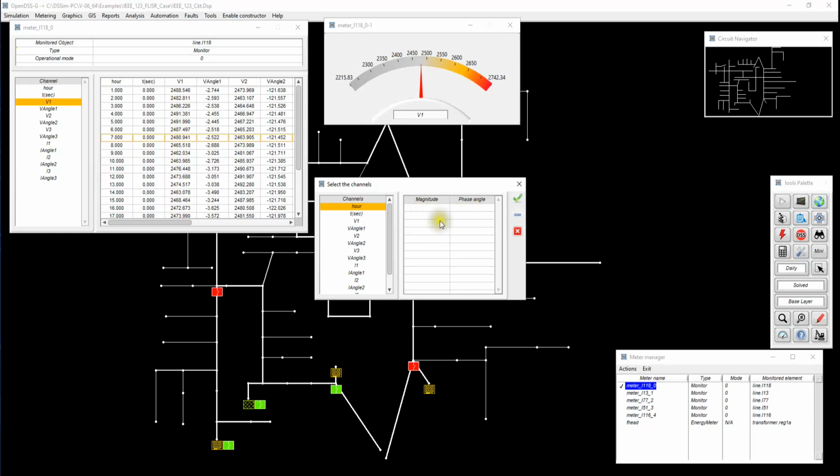In this case, just drag and drop each one of the components. For example, in this case, I'm trying to build a polar plot for voltages. If you want to delete one of the components, you can do it and then start over. Just as I showed on the screen, you will see that every time we create a pair, the channel will be checked to the left of this little panel. And once we click and create, the polar plot has been created.